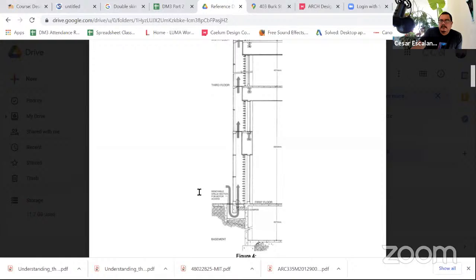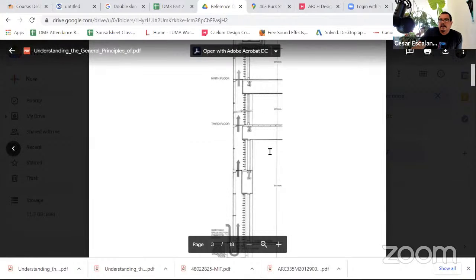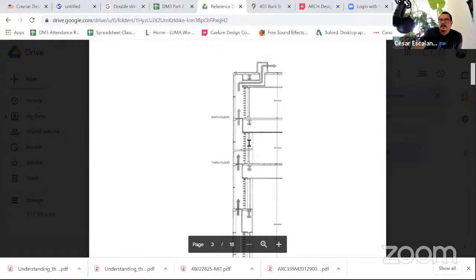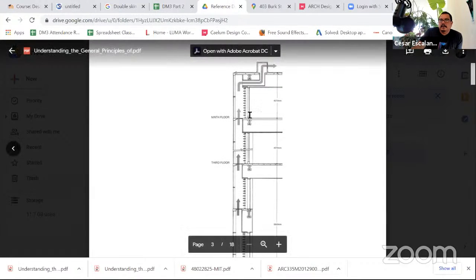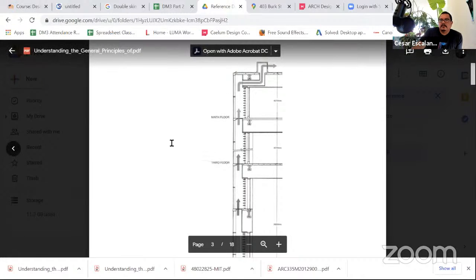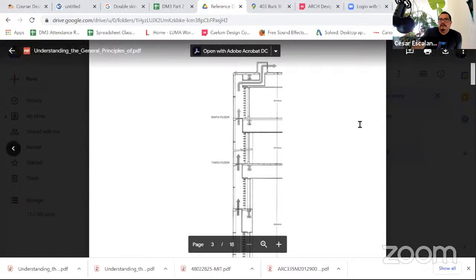exterior natural air is used as an intake to cool off the facade temperature in this cavity while keeping the sun control using these louver design windows, and creating a continued loop during the summer by allowing the heated air to flow upwards and away from the building.